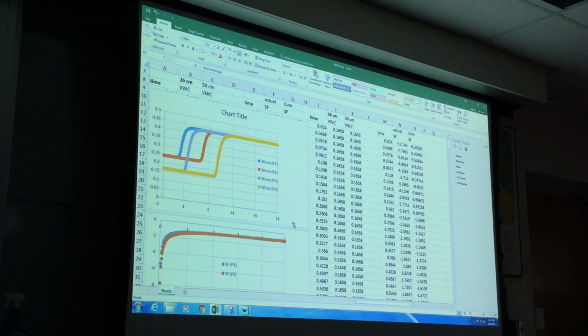But in terms of the theoretical aspects of infiltration, the drier the soil, because of sorptivity, the higher the initial infiltration rate. And then of course it increases until it reaches the saturated hydraulic conductivity. It cannot really exceed the saturated hydraulic conductivity. So this is basically the limiting factor. When everything is saturated, it levels off and remains constant.